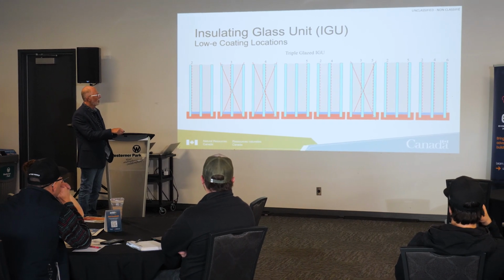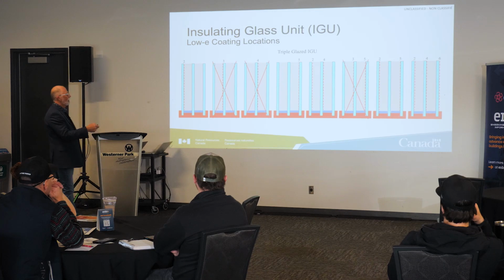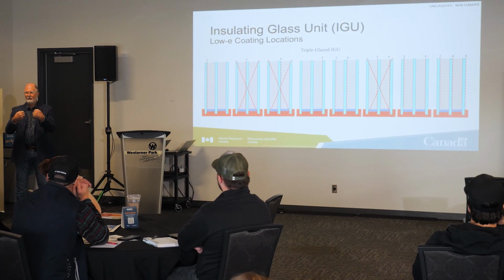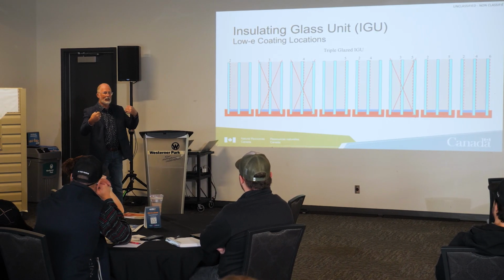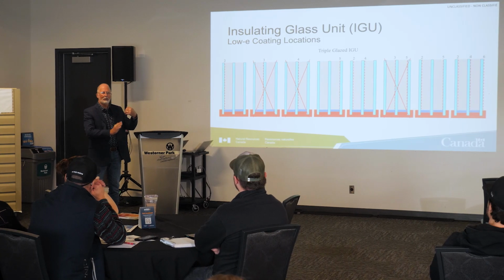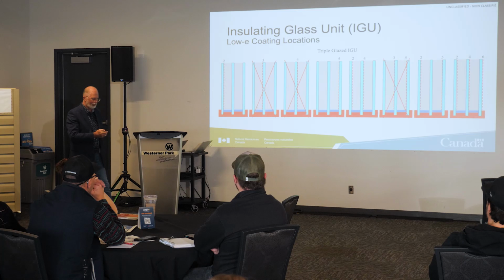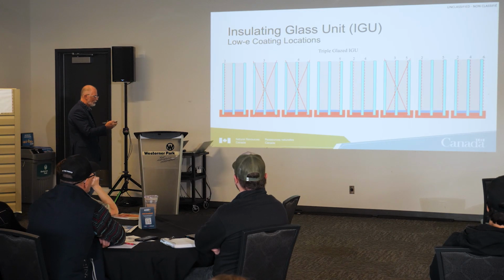The heat buildup here stays in this cavity. So we just don't have that bouncing back and forth when it's a single cavity. We can have the coatings on 2 sides of the cavity facing inwards as long as there's a separator in between them. Because remember, these are sealed units. Insulated glass units are sealed units. So those are some of the options in terms of triple glazing.